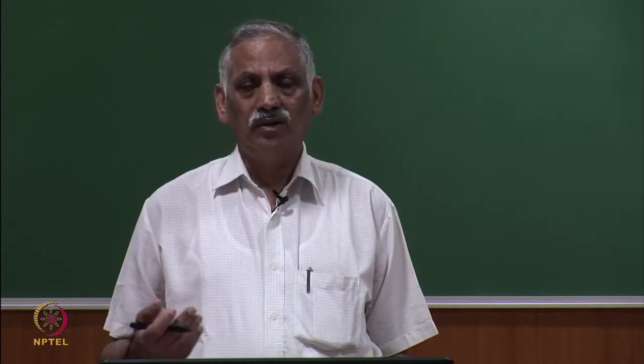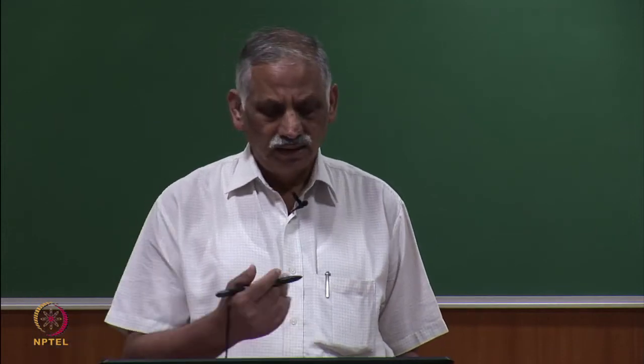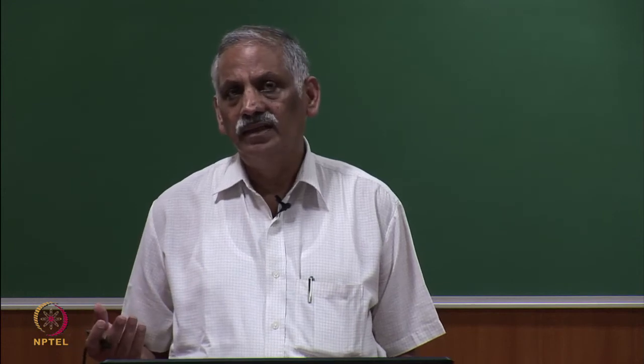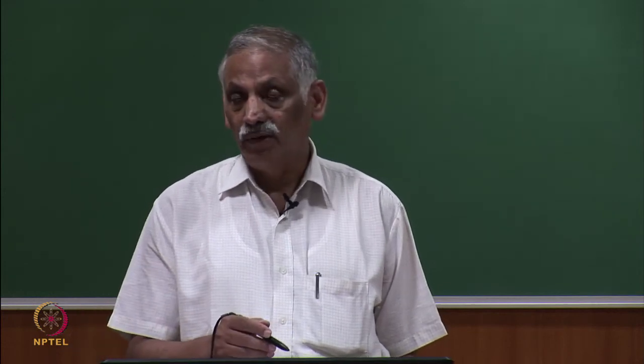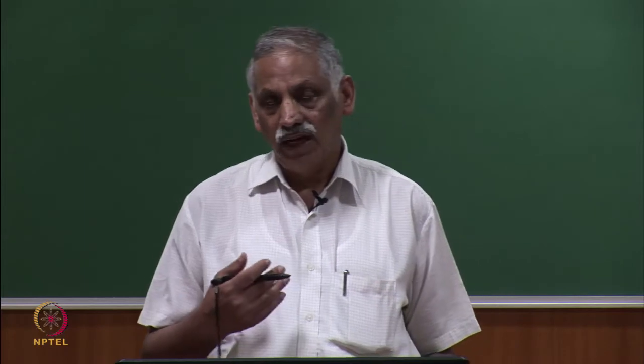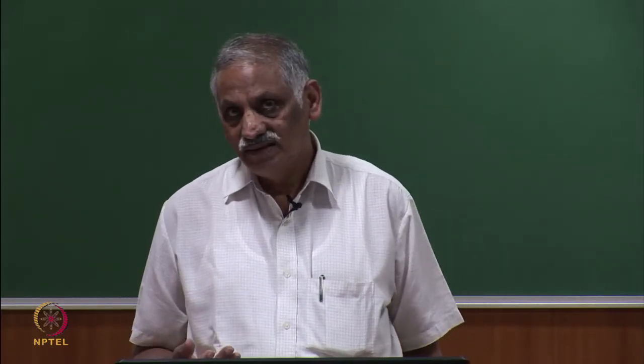I was talking about a diode rectifier with a capacitive filter and then load; you will get this kind of peaky waveform. But when this peaky current is drawn by the diode rectifier, when you are drawing peak current from the voltage, you will find the voltage becomes flat at the input. It will reduce because the impedance is there. So, it gets into a compromising situation, where voltage reduces and current increases.